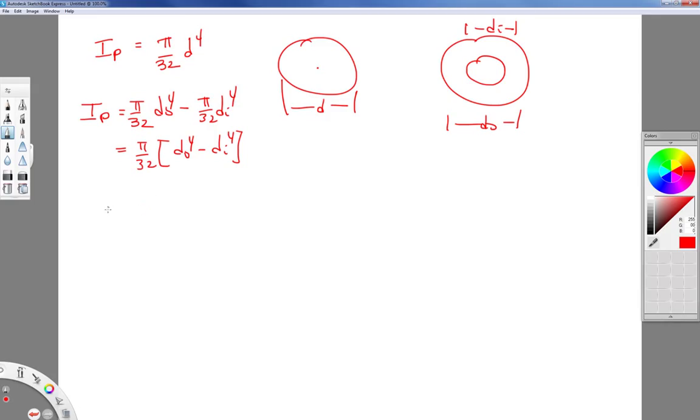All right, so let's write down what we have from our previous page. We said that the torque now would be equal to G times the twist rate times this integral that we're going to call I sub p. The other thing that we know from a few pages ago is that the shearing stress is equal to G times the twist rate times rho.